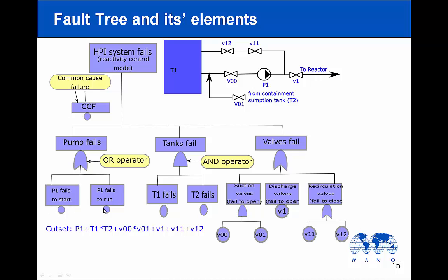For one pump, we distinguish fail to start and fail to run, since there are different initiators behind these failures. We also consider tanks, since they can be clogged, suction tank, or just empty after maintenance. Also, we have requirements for valves to be in a certain position: recirculation closed, suction and discharge open.